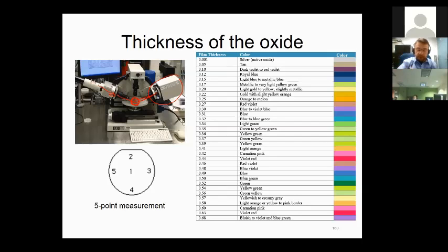That wafer, based on its characteristics, the thermally grown oxide on it or thermally grown nitride on it, it will alter the properties of the reflected light, and the photodetector will do some reverse engineering to sort out the exact thickness. But there are other ellipsometers, in that case you don't have to do this, but you might have to enter an initial estimate, a guess, as the user.